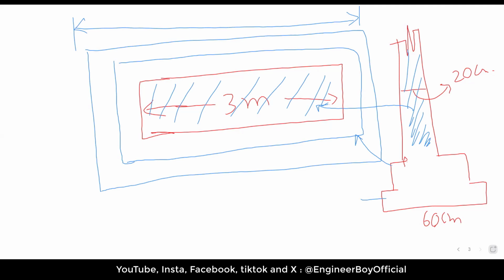So that should be the length of the wall, which is 3 meters, plus the factor which I have, which is the 60 centimeters, the width of the foundation, that is 0.6, and we will subtract the thickness of the wall, which is 0.20.